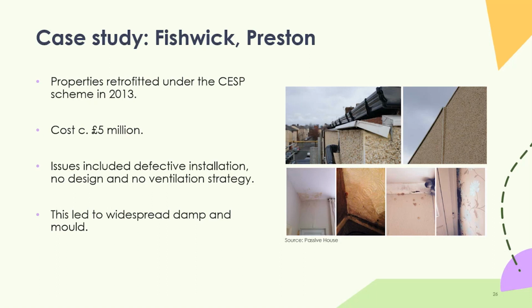The installation work, carried out by subcontractors, was rushed through, so people were really not given proper training, and the poor quality installation work combined with a lack of addressing ventilation issues allowed for problems all over the place. So you've got water being trapped behind the insulation layer.